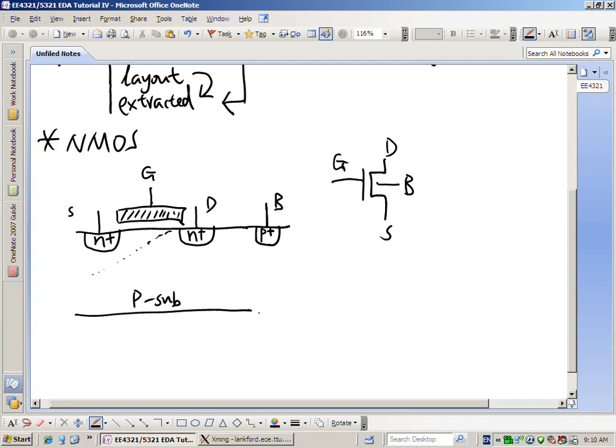This is a cross-section, and in real layout, we have to extend those terminals to higher levels of metal so that you can route the signal to the outside of the chip, right? So I can grow this via, and this via connects my source to the higher-level metal 1, and the same thing for the gate.